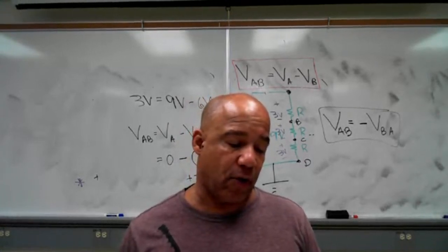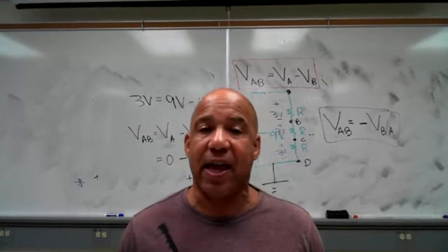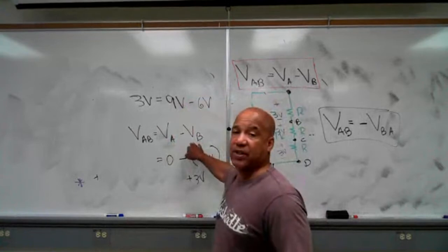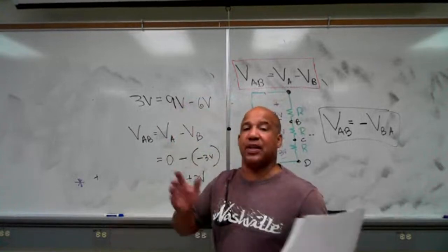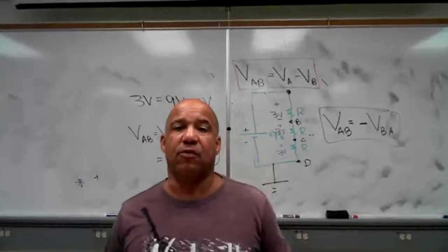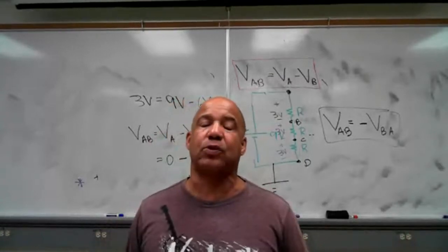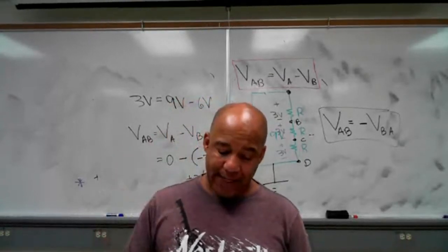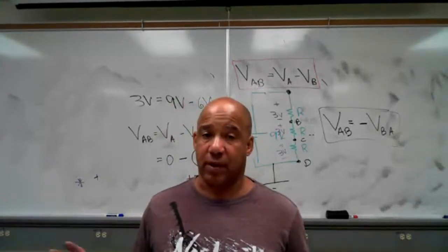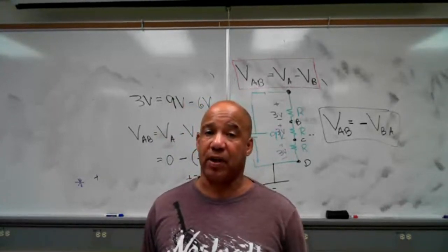And VC is 0 volts when in figure A, it was -8 volts. It's different numbers. But if you use this equation across your resistor, you'll see that you still have the same voltage across each resistor. Your reference point doesn't matter. The voltage difference between the 2 points will always be the same. And that is the purpose of this lab. So any questions on the theory part, what I just went over? Anybody have any questions?